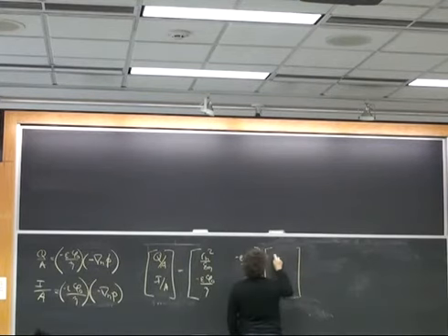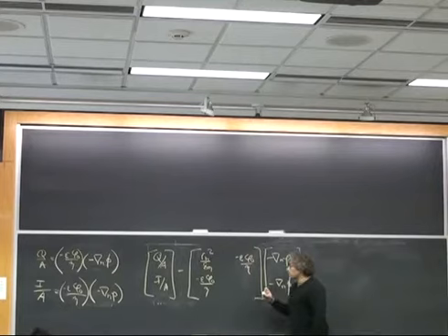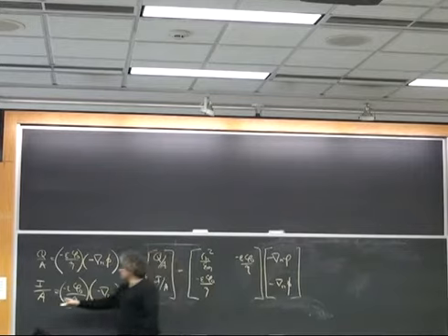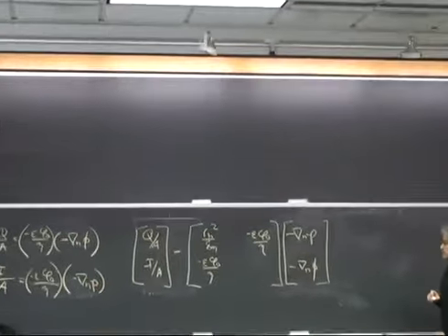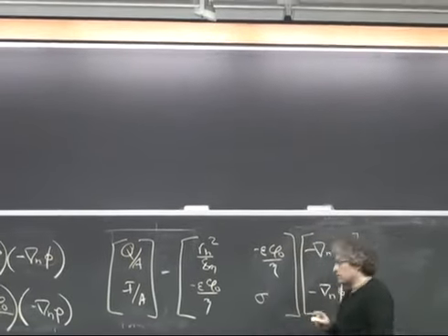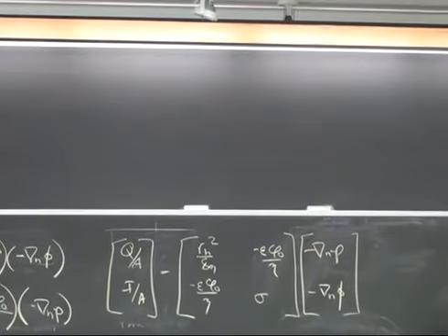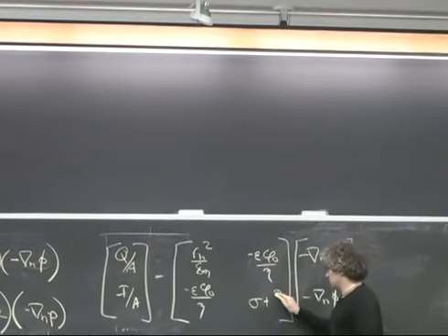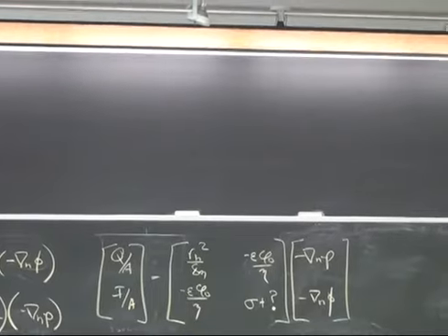And what I want to talk about next is I want to start talking about the transport of ions, and I want to relate that to the current that we see generated by an electroosmotic flow. And the reason why that is important is that, first of all, a basic understanding of ion transport will allow us to say that the basic answer for this chi-2,2 is the conductivity sigma. And that there's a correction factor to this sigma that comes from the convective surface conductivity.